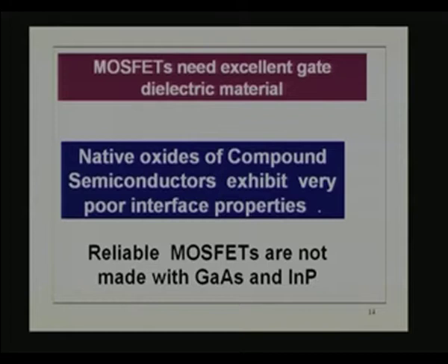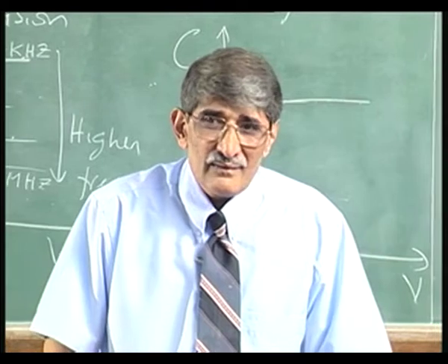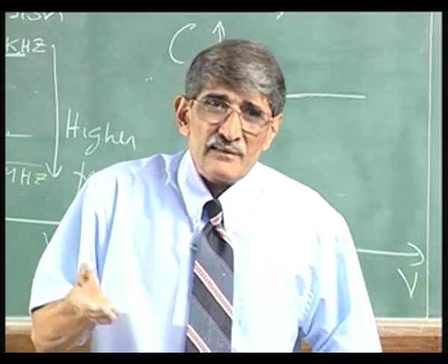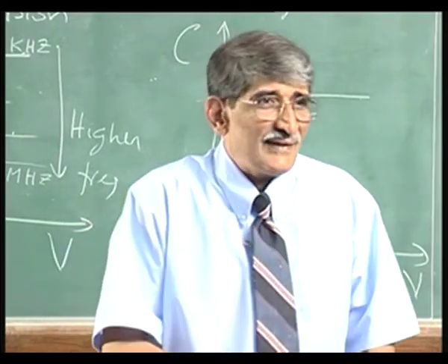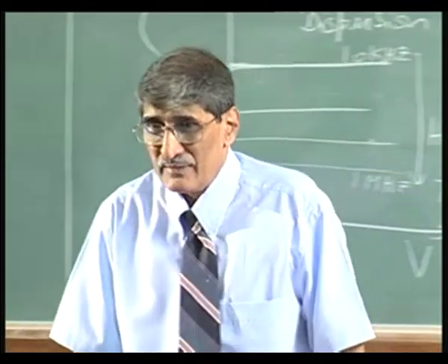So, reliable MOSFETs are not made with gallium arsenide and also indium phosphide. I just did not say indium phosphide. With indium phosphide, the situation is worse. Why? The vapor pressure of phosphorus is even higher than that of arsenic. So, you are in more trouble with indium phosphide.